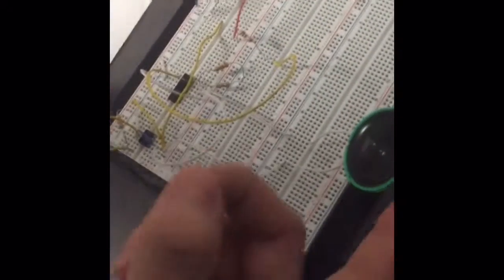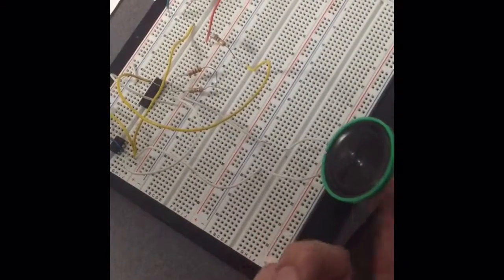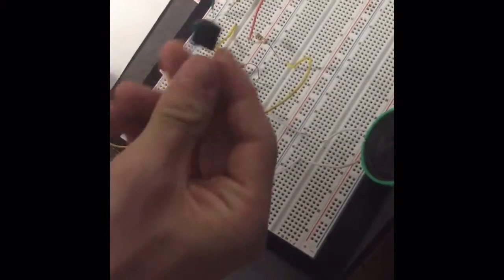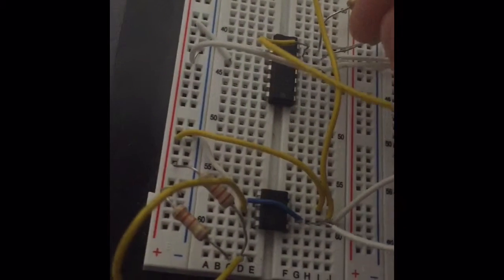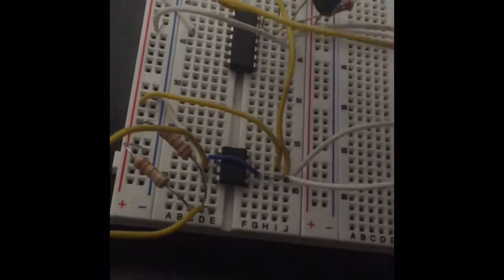All right. We also noticed that the signal is not very loud out of this amplifier, and it has a lot of noise. To get rid of some of the noise, but it dims the sound, you can put this capacitor from the output to the input on this node, and it will eliminate the noise, but it takes away some of the volume. Very clear on a loud computer speaker, though.